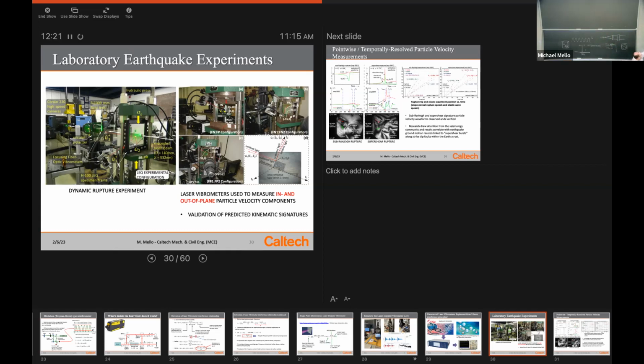It's being focused by this lens. See this big lens? Circular polarizer. Here are the polarizing optics ahead of it. Then that's being focused all the way down to this pair of fast, high-speed cameras that sit back here. So they're going to watch this stationary fringe pattern that we initially start with and how it changes as we make these surfaces slip. We're going to literally try to follow the rupture that travels along this interface associated with the failure of that interface to support the load.